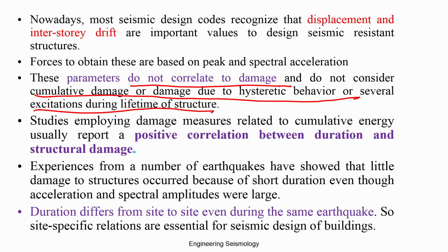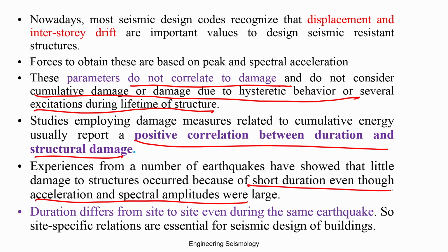So, scientists put effort into this consideration, and they found that studies employing damage measures related to cumulative energy usually report a positive correlation between the duration and structural damage. So, the duration is becoming a part of interpreting the earthquake record. Experience from a number of earthquakes has shown that little damage occurred to structures because of short duration, even though the peak acceleration amplitudes were very large. This was the observation they made.